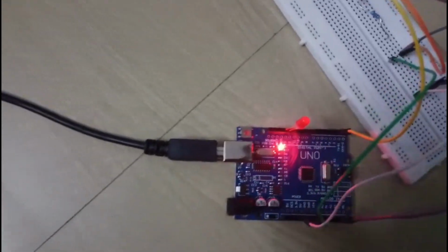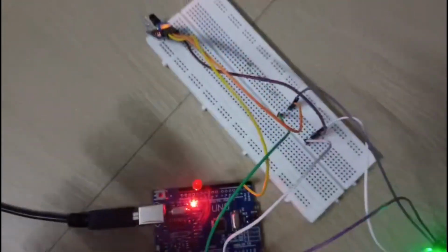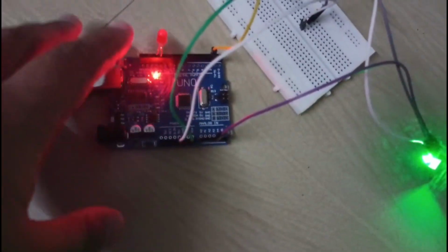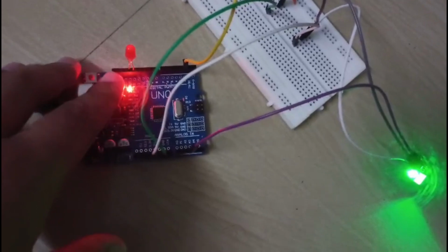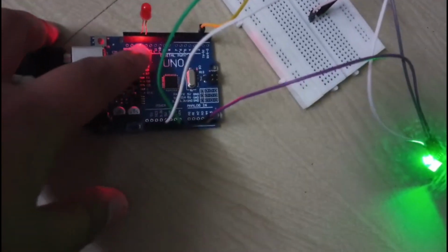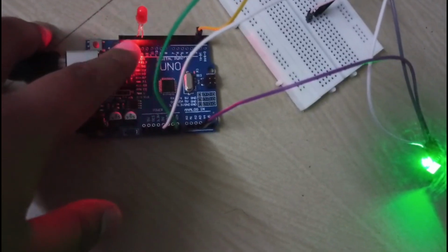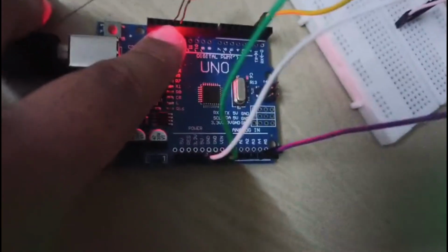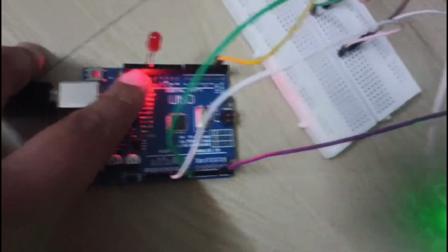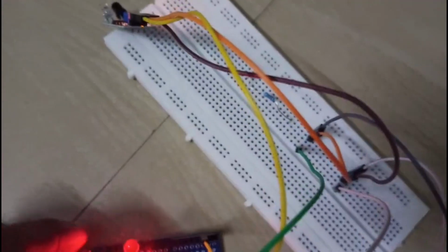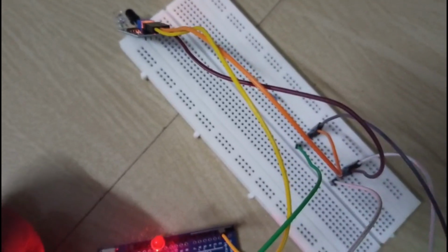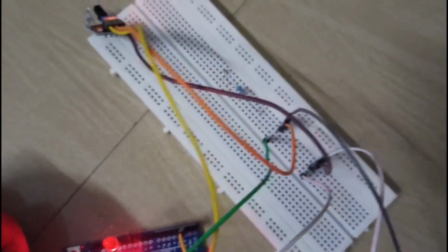Yes, friends. Now coming to the hardware components connection. Don't get confused, I will explain it simply. Since I don't have many resistors, I am considering a single LED and placing it on my Arduino directly. The long leg should be in pin 13 and the short side in the ground position. And this is my LDR sensor and this is my IR sensor. You can use IR or PIR as per your convenience.